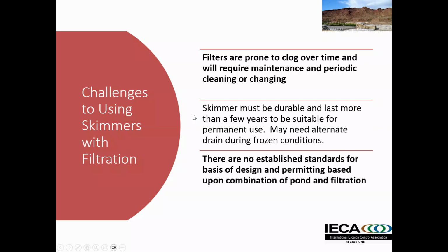And then lastly, the biggest challenge we have is there are no established standards for basis of design and permitting based upon the combination of a pond and filtration. Now, there are bases of design for filters. So typically they're looked at as a mechanical treatment device or MTD or some sort of proprietary device. Different MS4s have different regulations on those. Some of them have requirements to have certain approvals. Typically, there's a third-party testing requirement at a minimum. So you got to have some kind of manufacturer's data to base the TSS removal rate on. But that is part of the process.